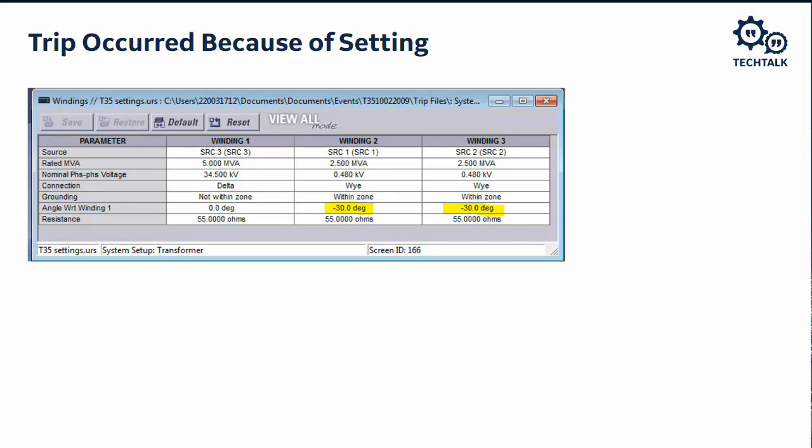And there was some strain bus that ran between the two. If we assume that the strain bus ran from north to south, that means as we look west, we would see one transformer. As we looked to the east, we would see a different transformer. If we look to the east and look to the bushing on the far left, that would be H1. But because these transformers were facing each other, they would be mirror images of each other. So if we look to the west and look to the bushing on the right, that wouldn't be H1.